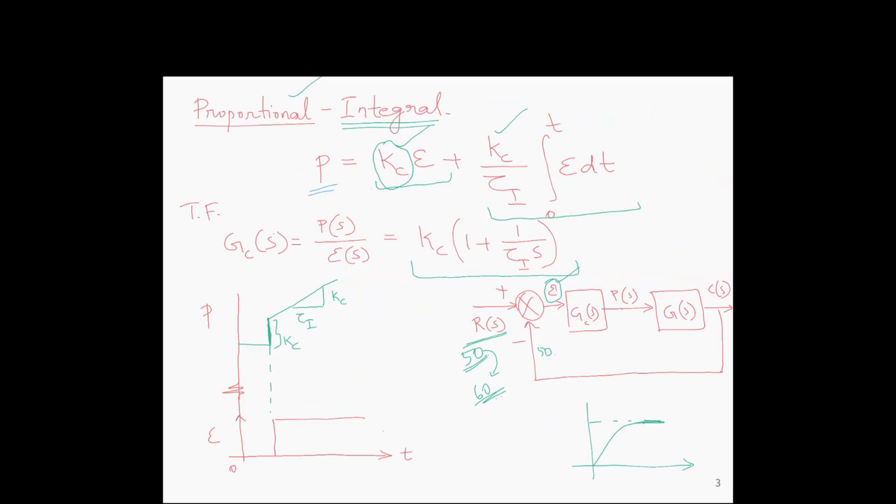So what happens? What is the response of the proportional integral controller? Until this step change happened, it was at some predetermined value, and whenever there is some sudden change, there is a response from the controller. This output P of S will be something like this. It will have a sudden rise, and the rise is equivalent to Kc. That is due to the first part. And there is some rise in Kc, and then it gradually integrates, it gradually rises.